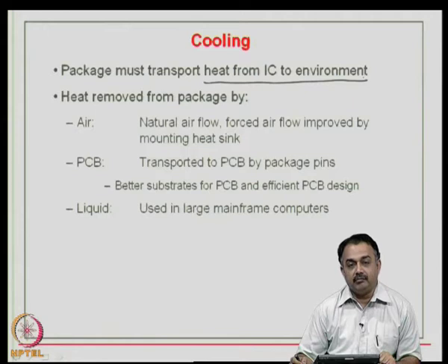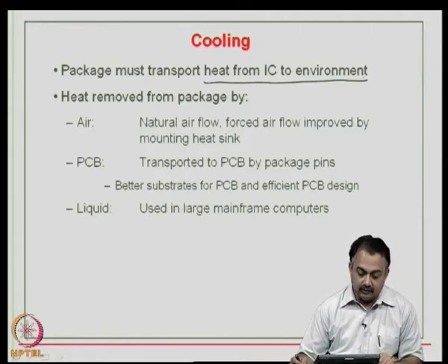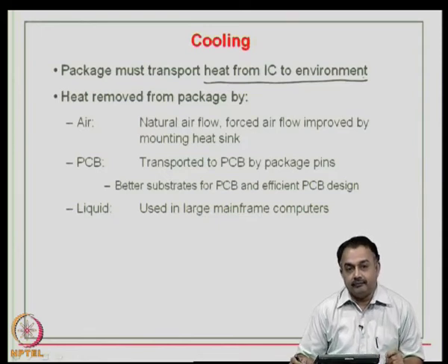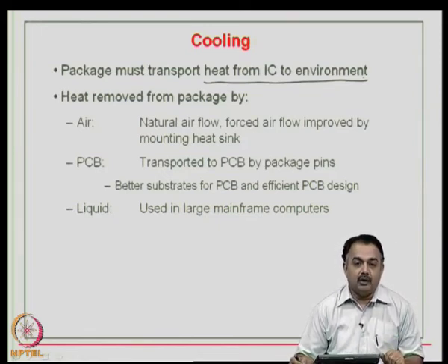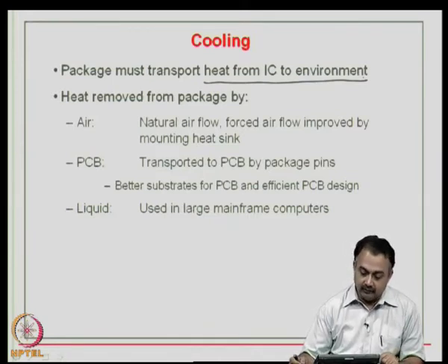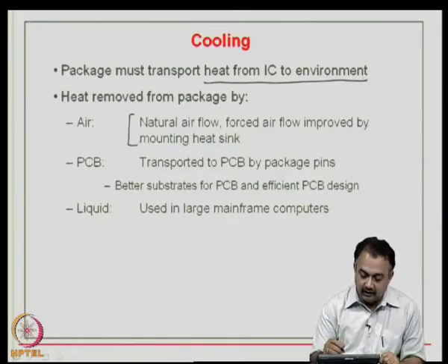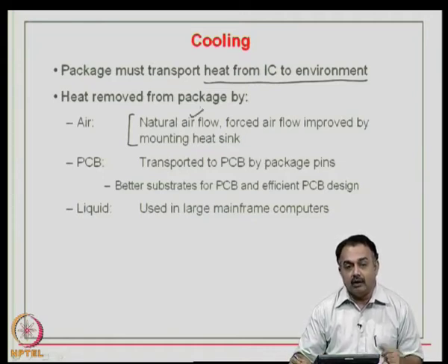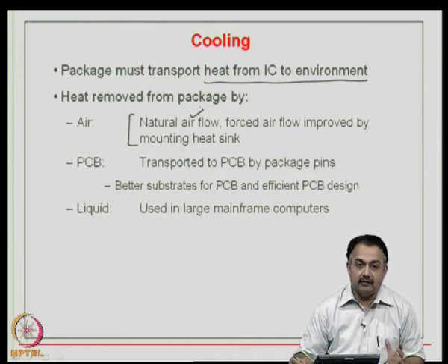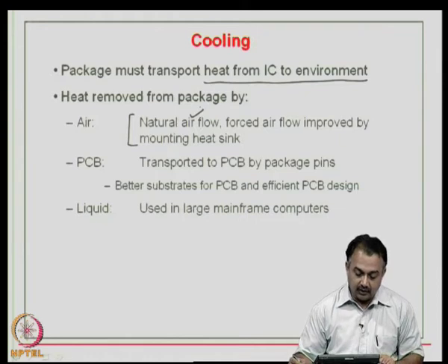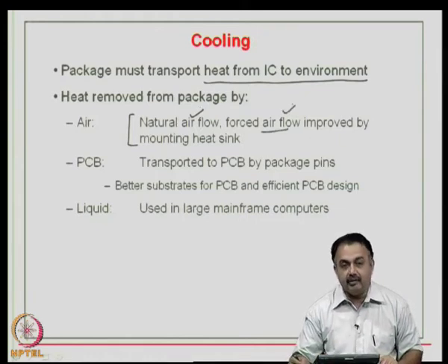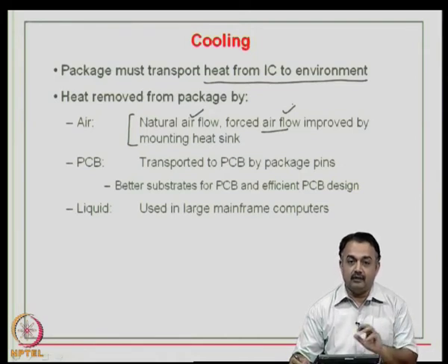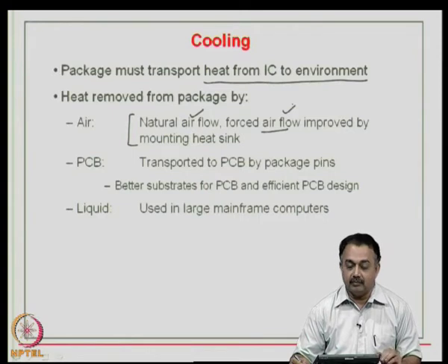Now, heat can be removed from the package by air. You have seen in desktop computers that there is a fan and you are removing the heat by forced airflow, okay, by mounting a fan. And there is also a methodology of using a heat sink. So, these are the two common methods that you will see, where either you can depend on natural airflow, but in some cases if the quantum of heat that is dissipated from the active device is large, then you will have to look at forced airflow, and that can be done by mounting a heat sink or using forced cooling by a fan or similar device.